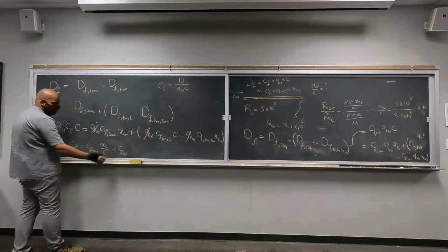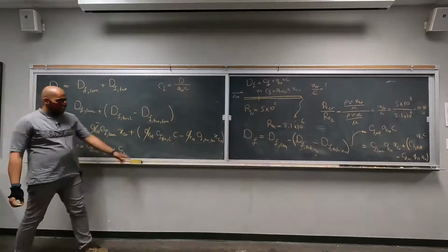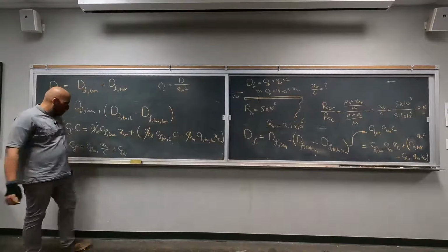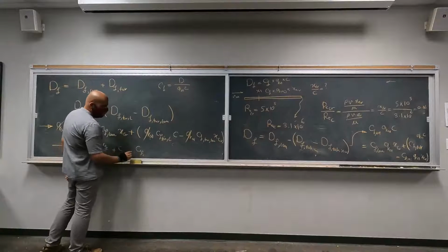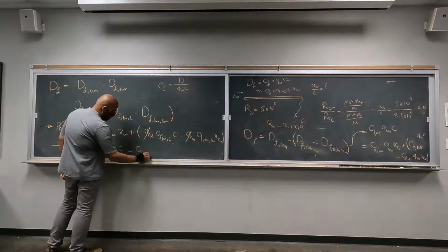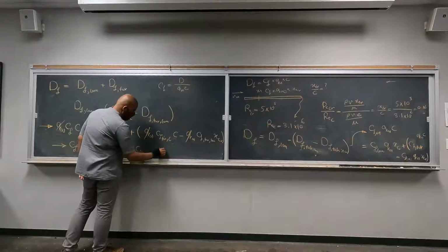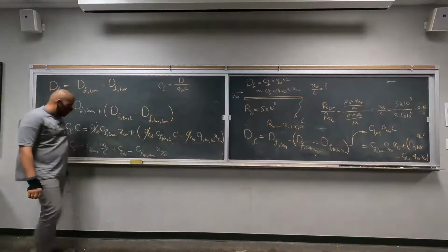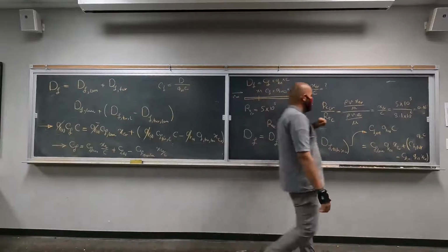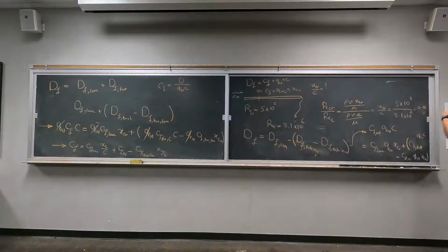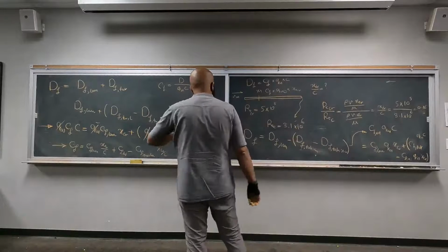This is the turbulent CF that assumes all of the plate is turbulent, multiplied by C divided by C is 1, minus CF turbulent for the laminar region, X critical divided by C. We already have the X critical divided by C, that's 0.16. The only thing we need to calculate are the CF.